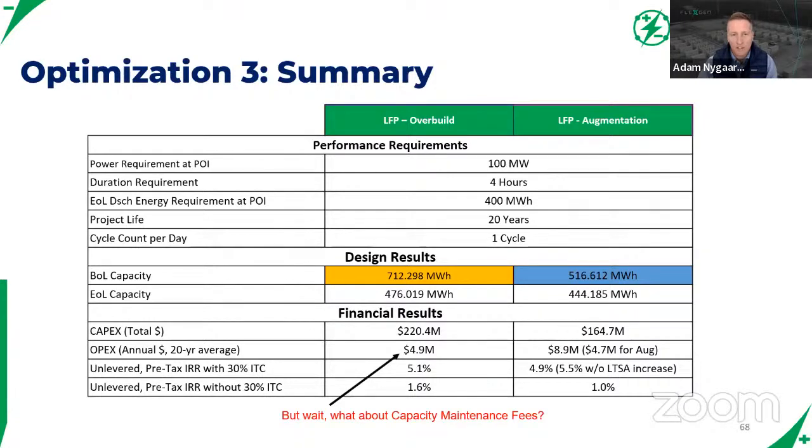And you then likely need to file an amendment. At that point, you may trigger a material modification, and then you have to go through an entirely long interconnection process to get that change approved. That's the likely result if you don't plan. If you don't plan up front for DC augmentation, then you will be forced to do AC augmentation and deal with the headaches of going through interconnection processes. Good point.